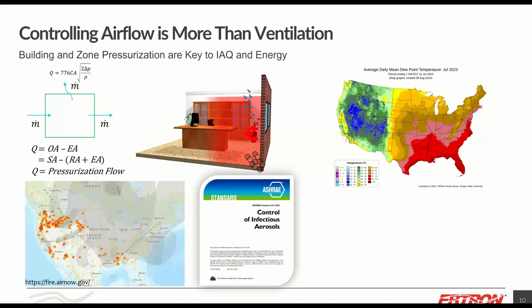Also, with Standard 241, which we'll address a little more in this presentation, pressurization is very important, just as it is in healthcare spaces. So you aren't providing air that has contaminants in it, bioaerosols in it, that are getting people breathing into a space that's supposed to be clean. You want the air to go from a clean space to a dirty space.